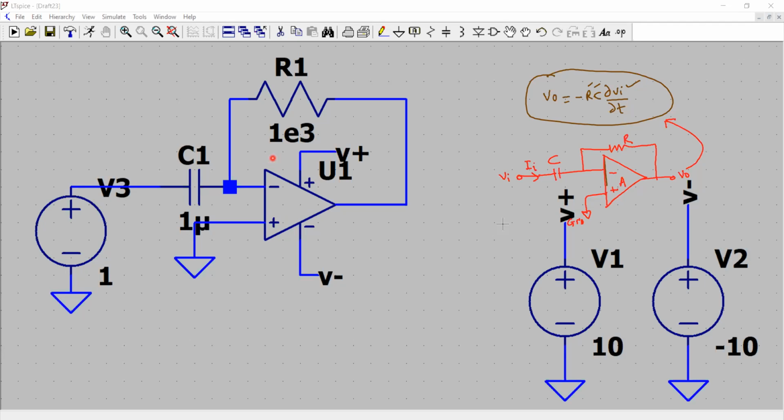So let us write how much that comes. The gain would be, let's say, 1 into 10 to the power minus 6 into 1 into 10 to the power minus 3. No, plus 3. That's the 1 kilo. So it's about 1 into 10 to the power minus 3. So in fact it's going to be an attenuator, right? So it's like minus 3.